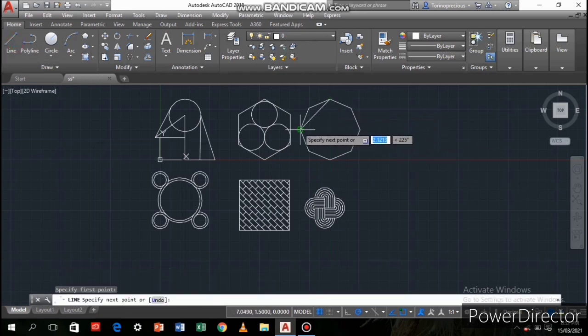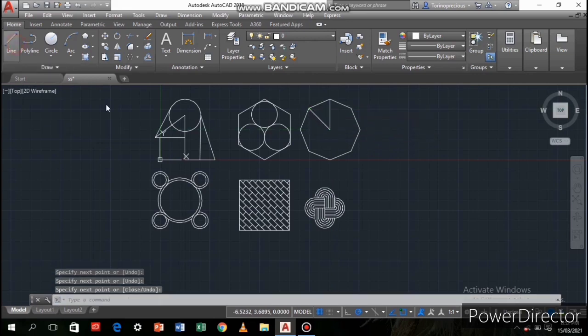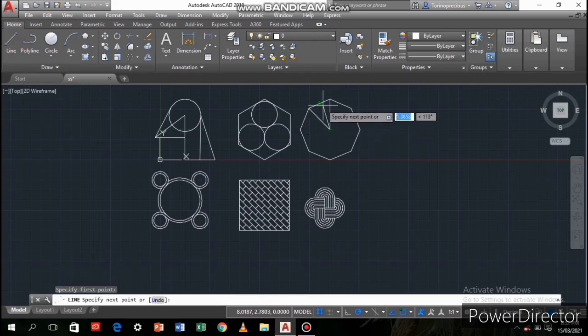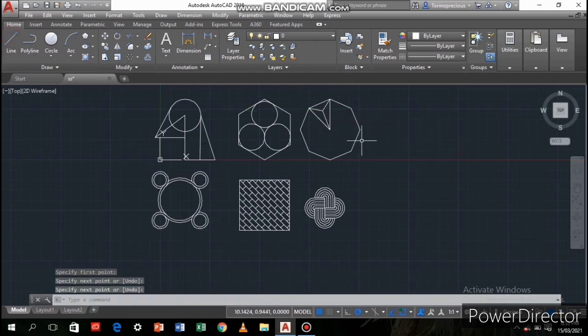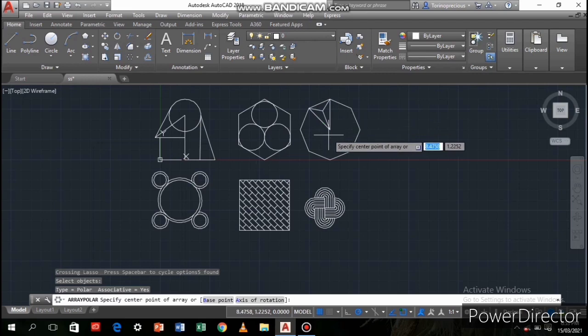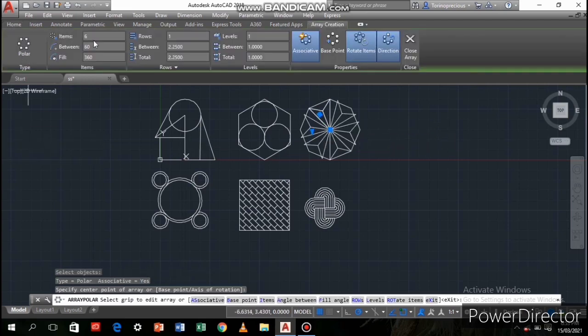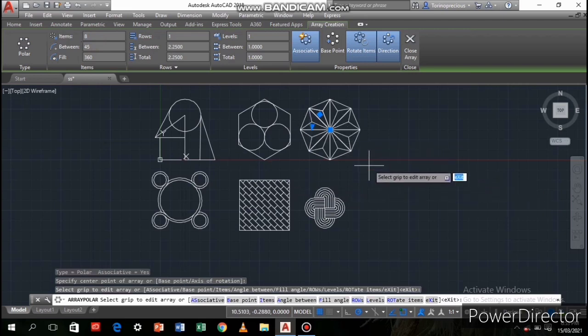First, create a triangle from 2 consecutive points in the center. Next, we will make a bisector-like line with its length of 1 unit. Then let's connect this point to make it enclosed. Lastly, create a polar array of 8 with this figure. Change the item to 8 and that's it.